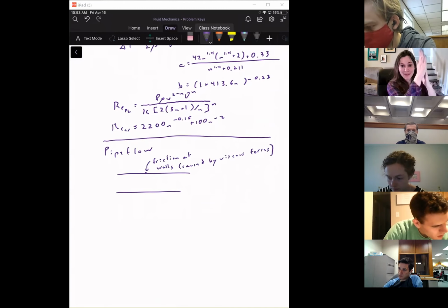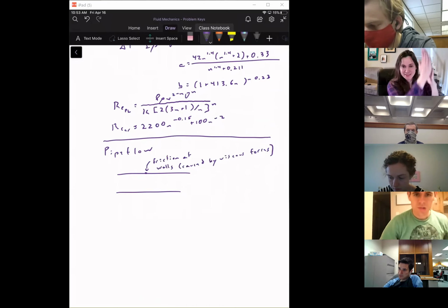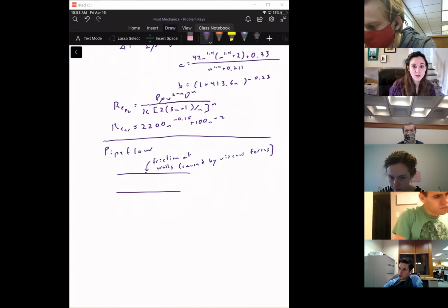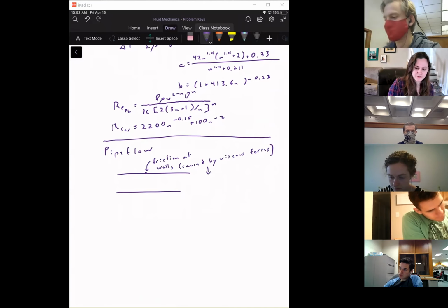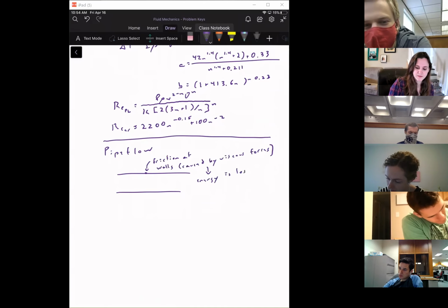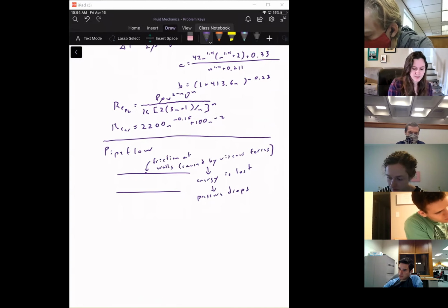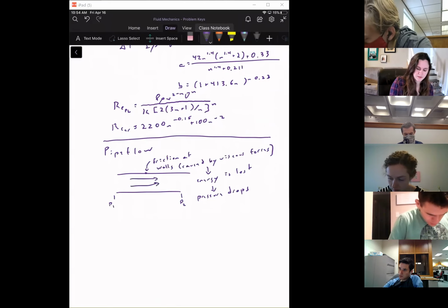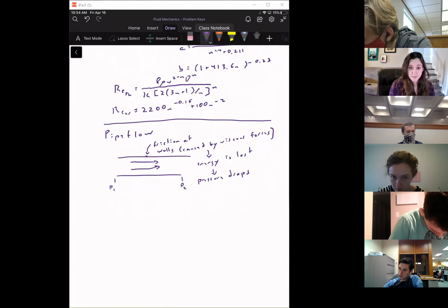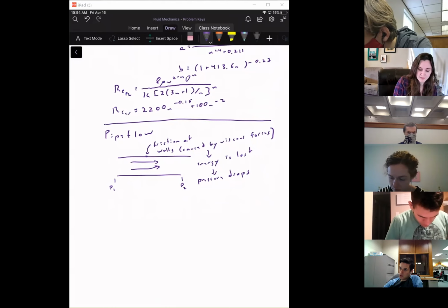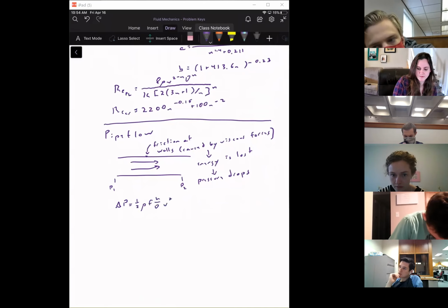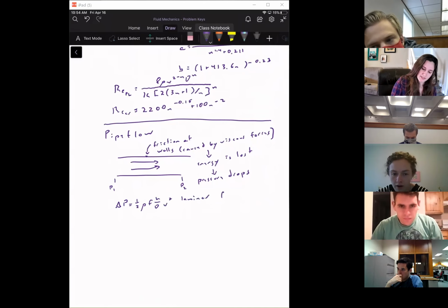And I like to think about that as, once upon a time, I made you do this. And I said, see, when you rub against something, shear creates friction. You can feel that. So friction at the walls is caused by shear forces. Energy is lost. Pressure drops. Okay. And then also, pressure drops according to that same equation I wrote for the non-Newtonian fluids. Or for laminar, f is equal to 64 over Re for round pipe.